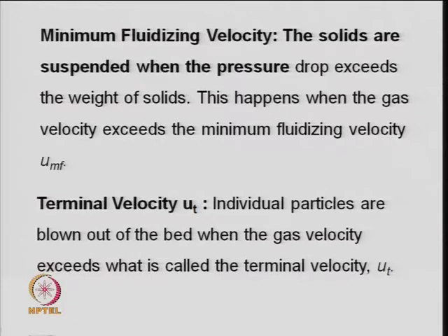Then there is another term, minimum fluidizing velocity. You need to design the reactor for this, and it will depend on the type of solid material and the gas. As the name says, it is the velocity required to fluidize the bed, to keep the solids in suspended form, because the gravity force is always acting vertically downward. To overcome that, a buoyant force is required, and that is what the superficial gas velocity provides. It is the volumetric flow rate of gas divided by the cross-sectional area of the tower.